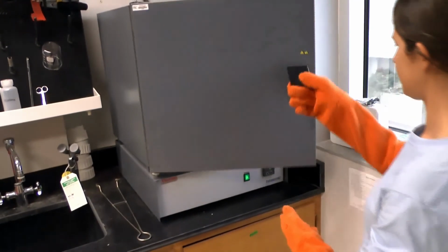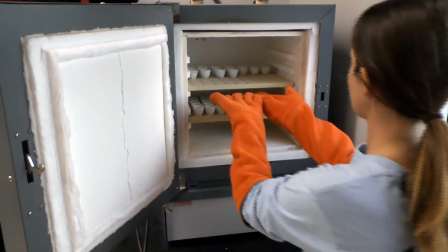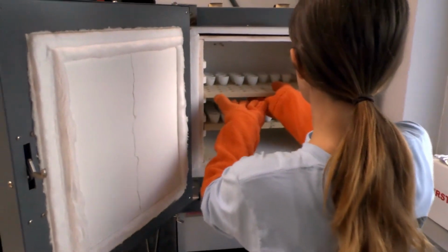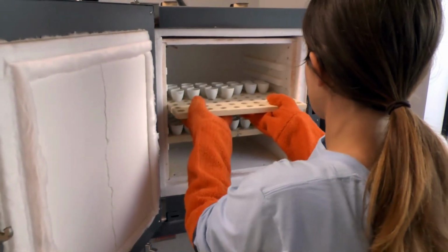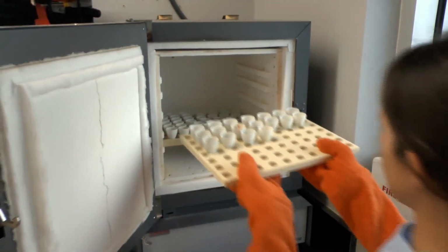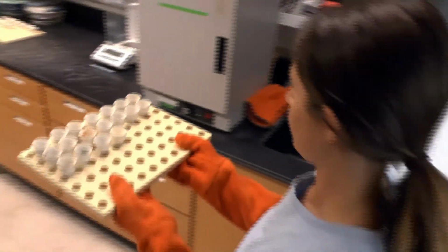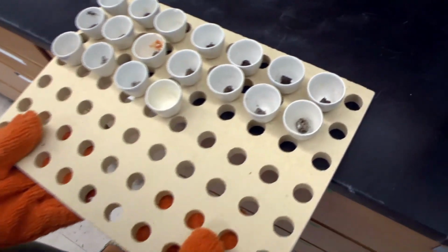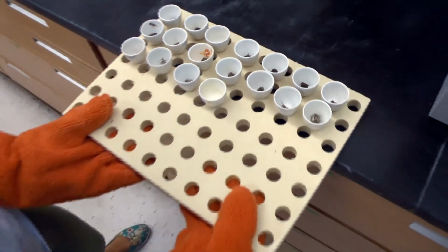If you wish to determine the amount of inorganic carbon in the soil, you can combust the sample again at 950 degrees Celsius for 1 hour. The additional amount of weight lost is due to combustion of carbonates in the soil. The ramp time and cooling time needed for the furnace to achieve these temperatures will vary by manufacturer. Equations for the calculation of organic matter, organic carbon, and inorganic carbon can be found in the manual accompanying these videos.